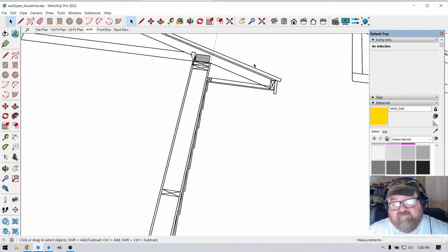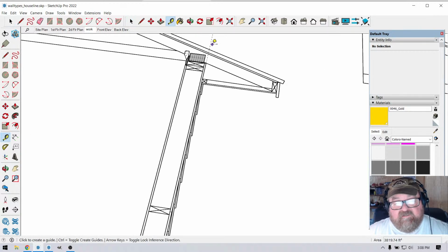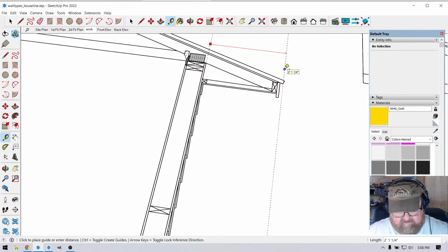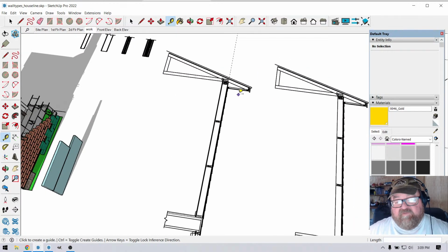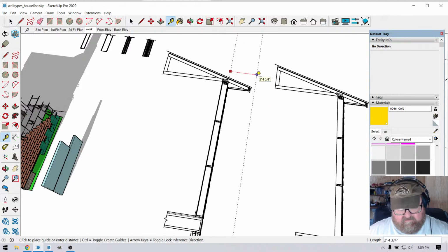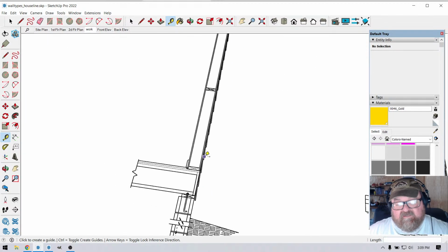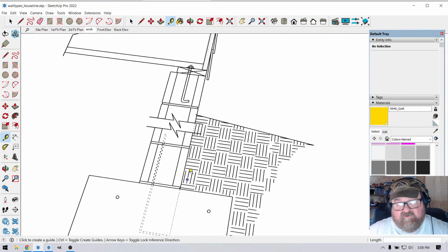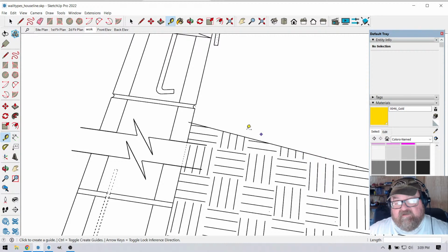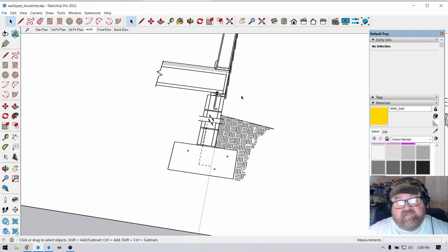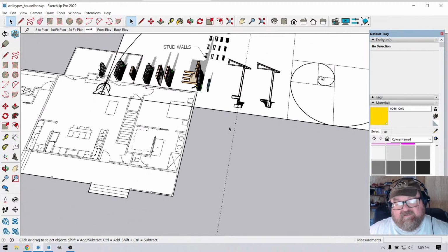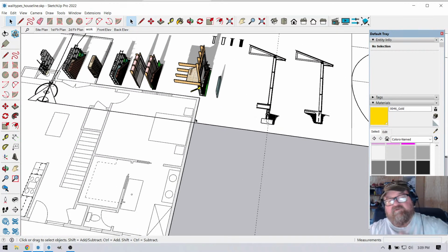Did you know that you can have 2 feet of your roof overhang into the setback? The only time you have to really worry about that is, like I said, if you're right on the setback. So he doesn't concern himself with any of that, or the siding or anything. He comes down to this point right here, because that's the grade, and he will establish this point right there, that little intersection. That's the house line. That's the one you're concerned about. And again, you're thinking, oh, this doesn't matter. It matters.